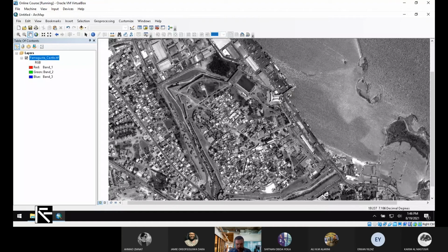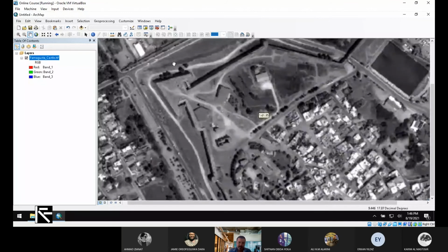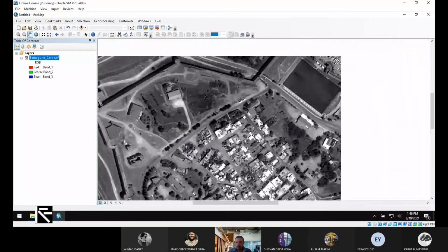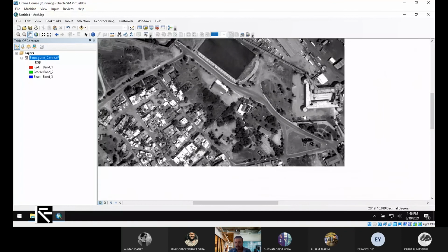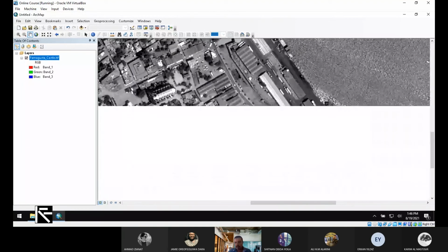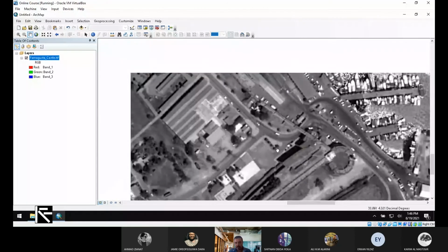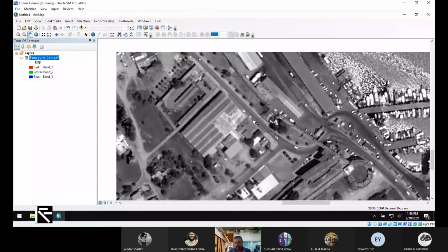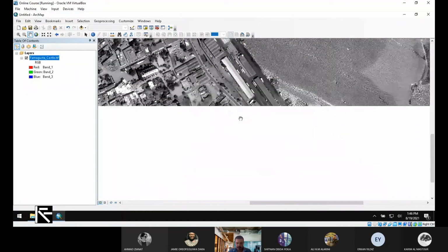For instance, go to the castle corner, stay there and take one point, then go to this football pitch and in one of the corners get another point with your GPS, then maybe go to the port or next to the wall, or in this factory or in storage, take another point and then come here and say this point equals this number, the other point equals those numbers accordingly.